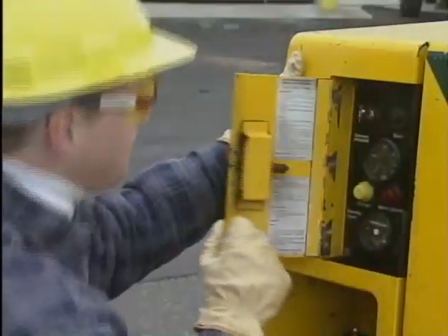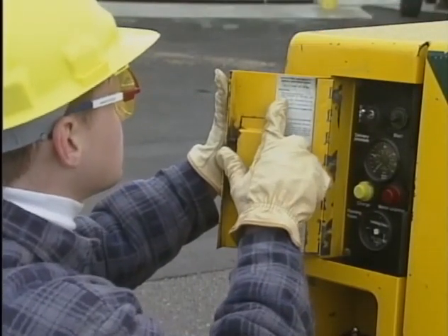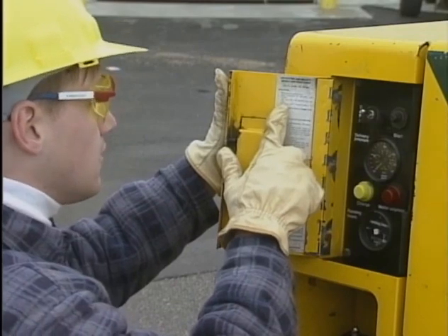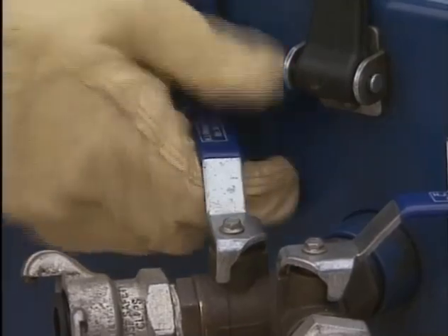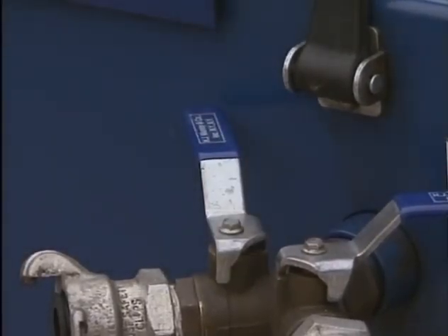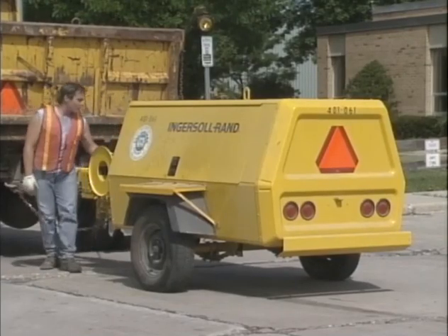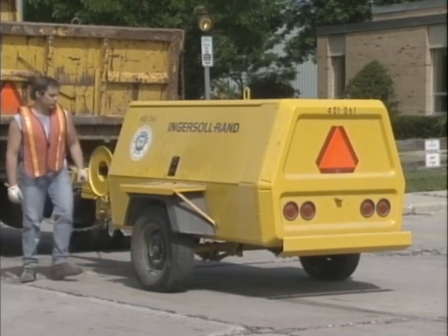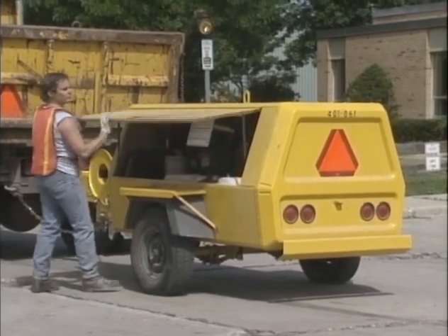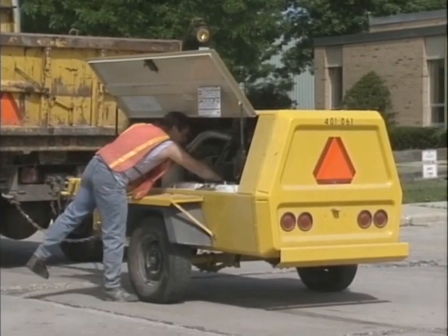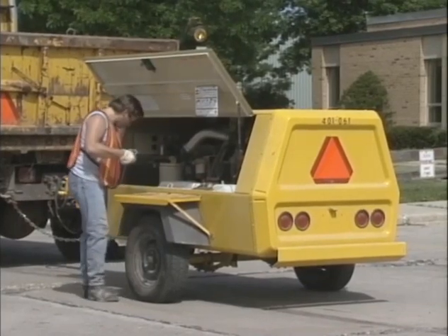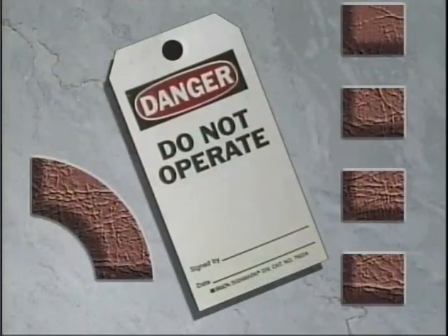Know your machine. Familiarize yourself with controls and instruments, their locations and functions. You'll handle controls without slipping if you wipe levers and knobs clean of oil or grease. Are repairs made? If your daily check uncovers any item that needs attention, repair, replacement, or adjustment, report it promptly. The most minor malfunction could be the result of more serious trouble, or can cause it if the machine is operated. When in doubt, attach a Do Not Operate tag to the control panel and disconnect the battery.